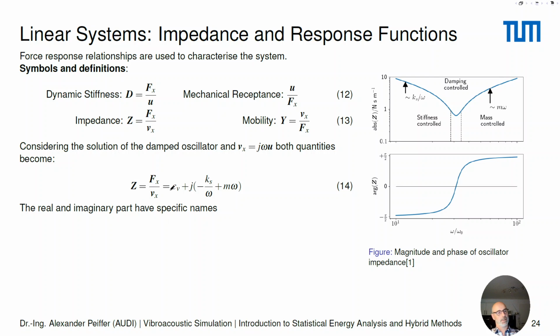So we have our critical or viscous damping plus a pure complex value, which is a term that depends on the stiffness and the mass with different relationship of omega. So we see for high frequencies the mass term is more important, and for lower frequency the stiffness term will become much more important. And this is what you get if we write the absolute value of the impedance.